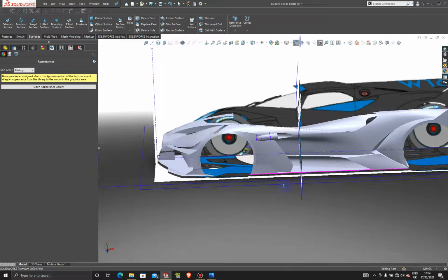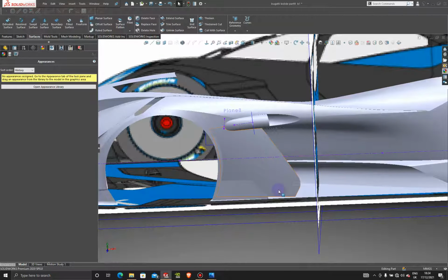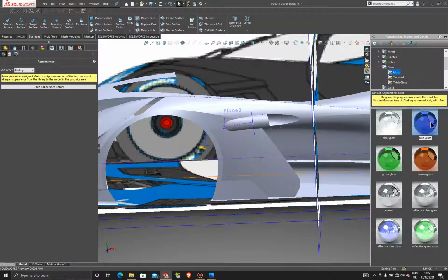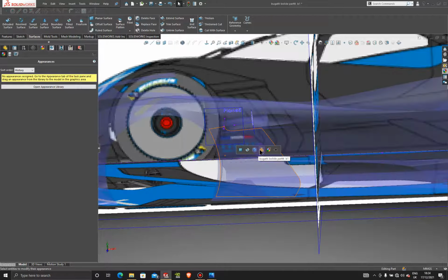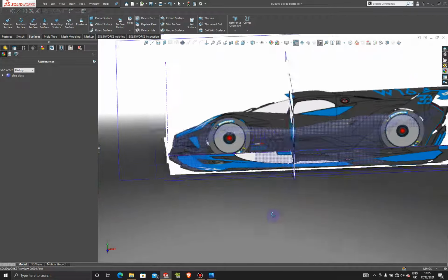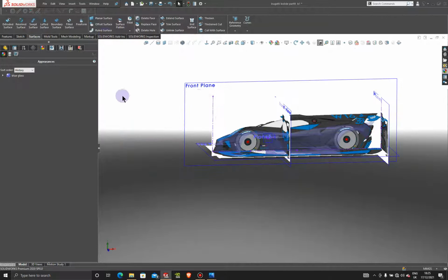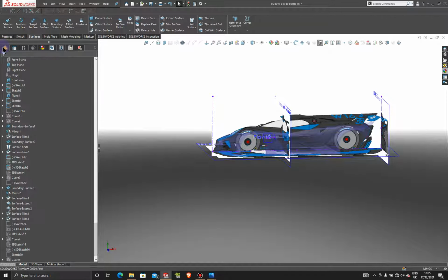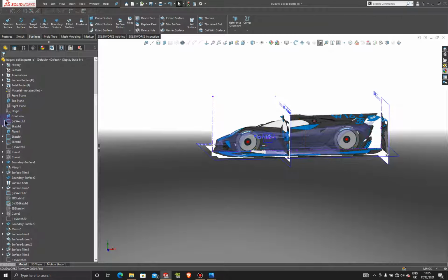Alright, so let's go on and cut out the second split here, a second gap here. So we're going to draw back our glass appearance on the whole thing, right? And then we're going to make another sketch on the front plane. Oh, we just hid some plane here, which I didn't want it to do because I'm moving too fast.